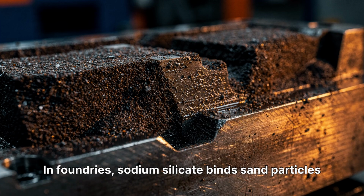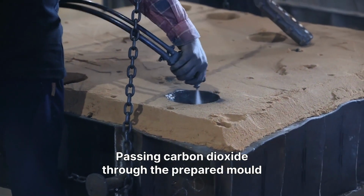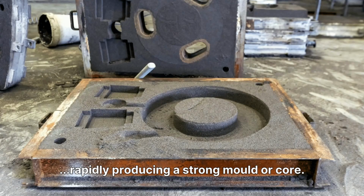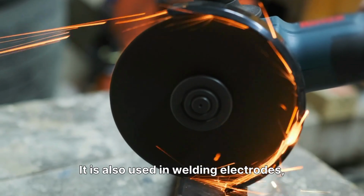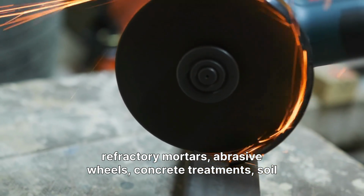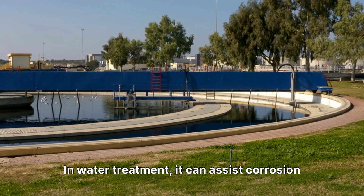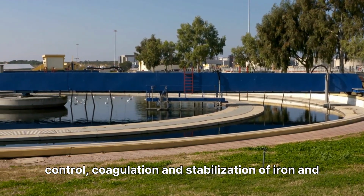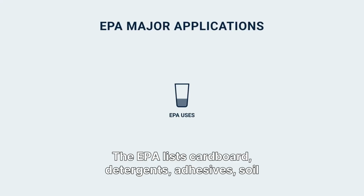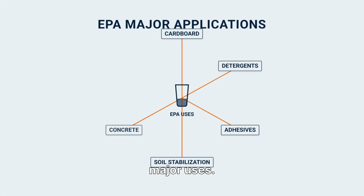In foundries, sodium silicate binds sand particles together. Passing carbon dioxide through the prepared mold converts the liquid binder into a hardened silica gel, rapidly producing a strong mold or core. It is also used in welding electrodes, refractory mortars, abrasive wheels, concrete treatments, soil stabilization, and drilling operations. In water treatment, it can assist corrosion control, coagulation, and stabilization of iron and manganese. The EPA lists cardboard, detergents, adhesives, soil stabilization, concrete, and water treatment among its major uses.